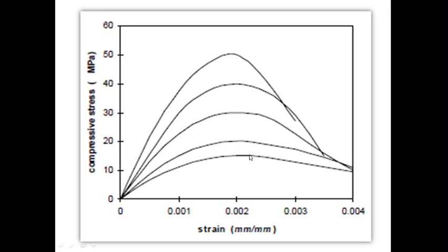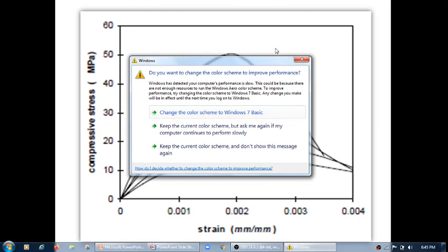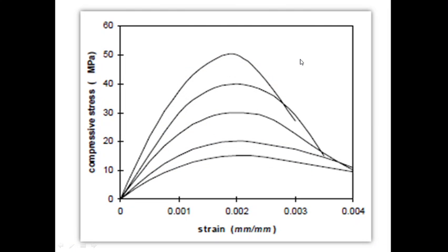And nowadays we know that in cities like Mumbai, or for that matter many metropolitan cities across the world, in skyscrapers and infrastructure projects, they are even using M100, M120 grades of concrete, but still we are using the strain of 0.0035. So suppose, for example, we use M80, M100 or M120, the concrete will try to become more brittle. So it will show more strength, but the failure strain will be less.